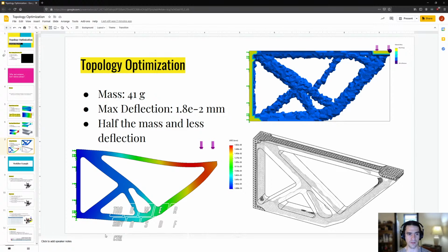So an understanding of load pathing is critical. However, sometimes you've got a lot of loads, complex loads, complex geometry. Maybe the load pathing isn't super intuitive, and you're shooting for something pretty optimized, and you just don't want to guess and check 100 times trying to come up with something. So that's where topology optimization comes in.